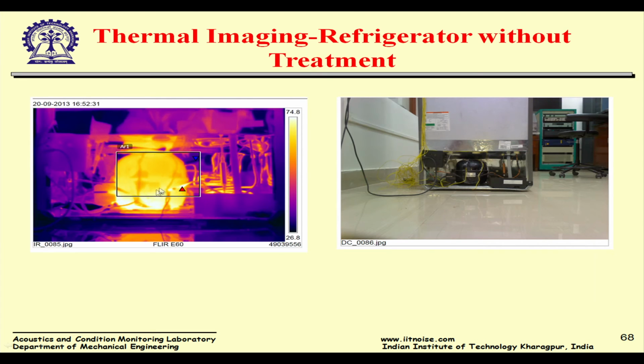This is through the thermal imaging camera, you can see, and here a lot of thermocouples have been put in the refrigerator, compressor, cabinets, etc., so that we are monitoring the temperature and logging it for many hours after we have done the treatment in this refrigerator to reduce the noise. Okay.